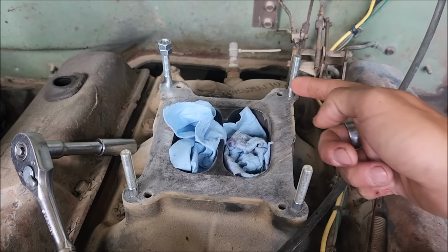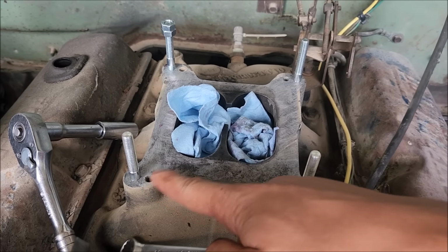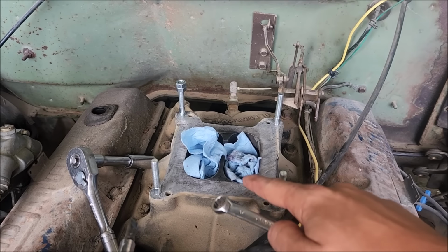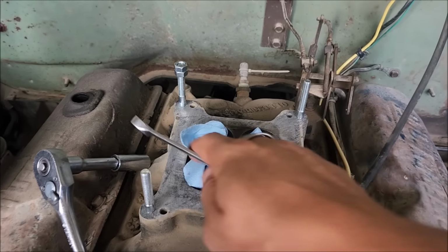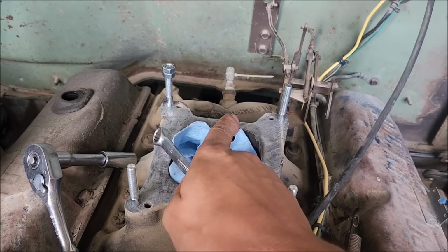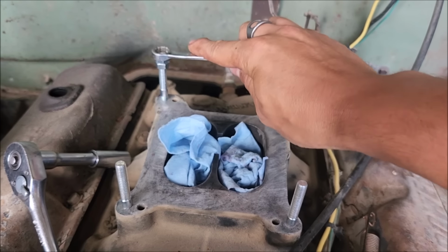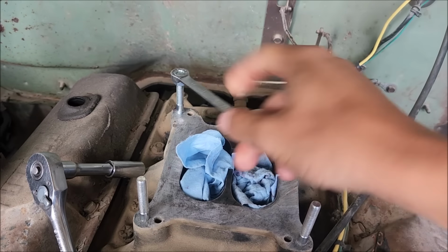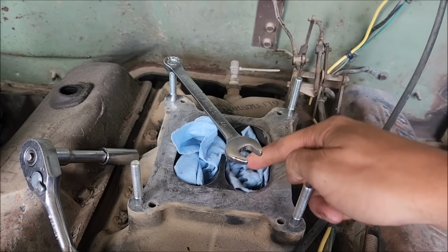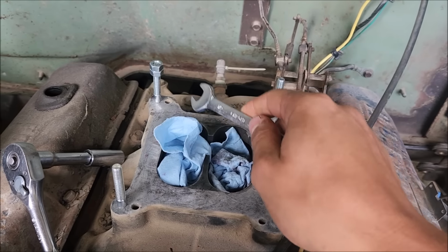So getting your carburetor studs here installed for the spacer, you just don't be lazy. Make sure you run them down all the way. What, do you want to be that guy that has all these different length carb bolts? Of course you don't. So you can do the same trick, just jam nut it. Some of them could be tight. This intake manifold's ancient, so this one was a little tight here, just a simple jam nut, and then we can run it down same as the others. And again, you want to keep your rags in your intake through all this, because it would really ruin your day if you drop something in there.